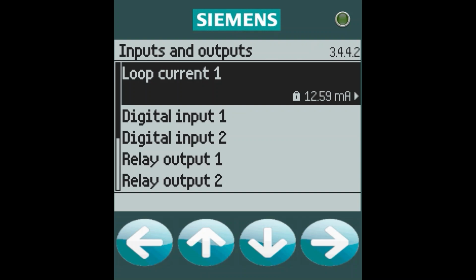So if I now enter a bad status, we're going to see that milliamp jump down to just below 4 milliamps, as is the Namur spec. And then if I go back into a good reading again, we'll see that come back up to whatever we had it set as. And again, I can change my measurement value and adjust that milliamp setting.